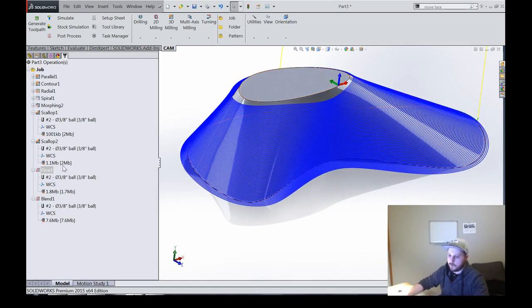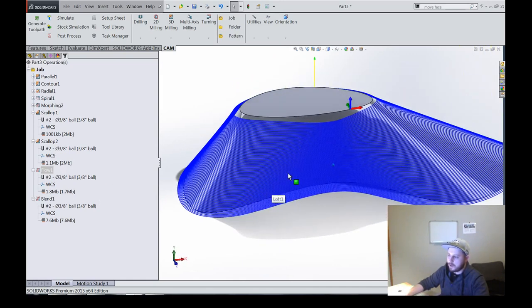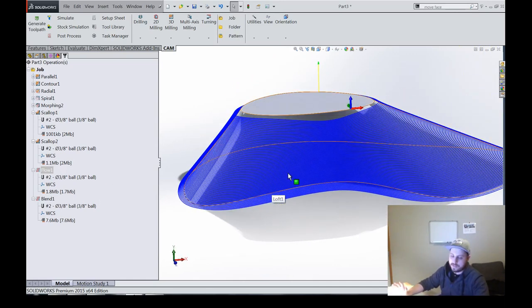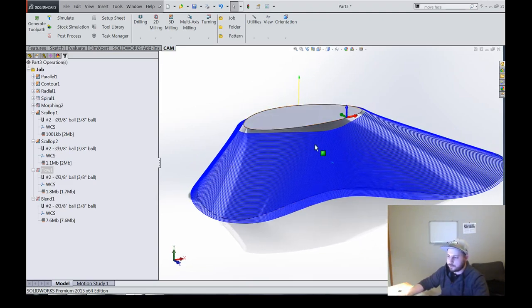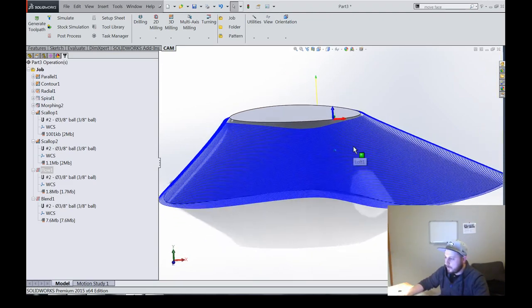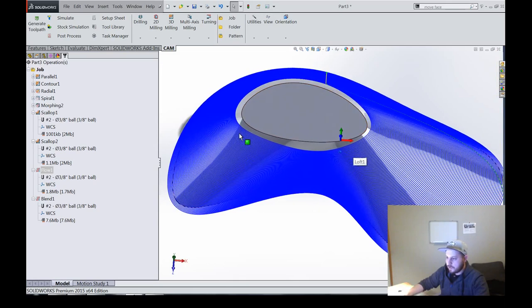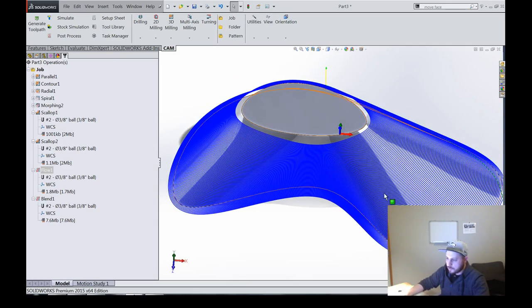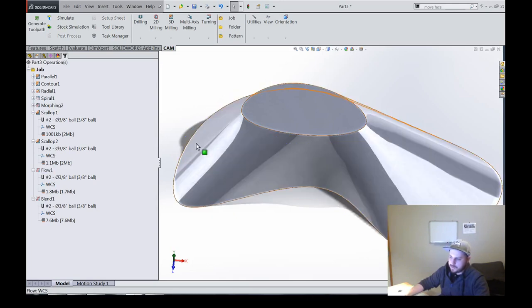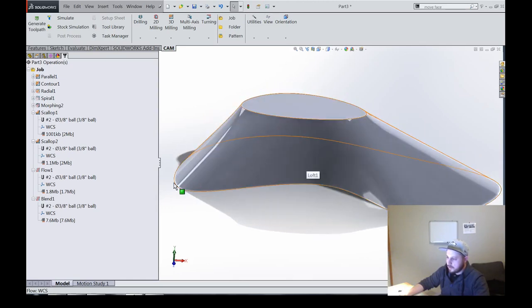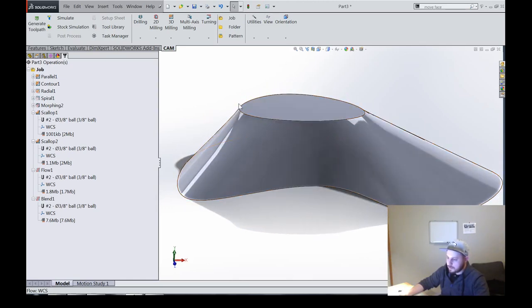Let's real quick go into the why. This is basically the quick rundown of why it's being superseded, and why I'm guessing you don't have it in Fusion. Nobody's ever explicitly told me this, but basically Flow is driven off of the UV vectors of the surface. I might have gone into this in another video, but imagine the surface is being built with a loft, with this curve and this curve morphed together over some distance.